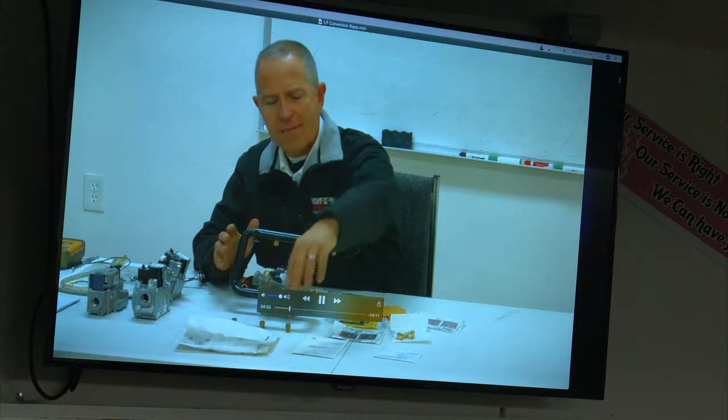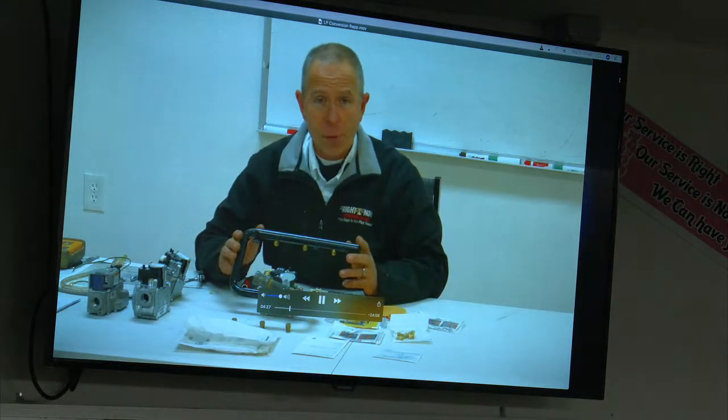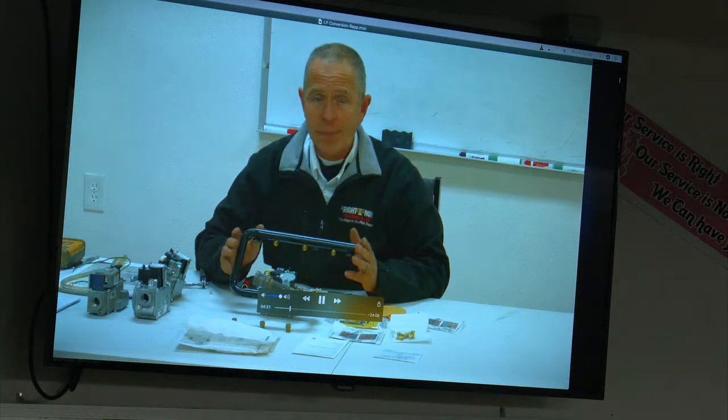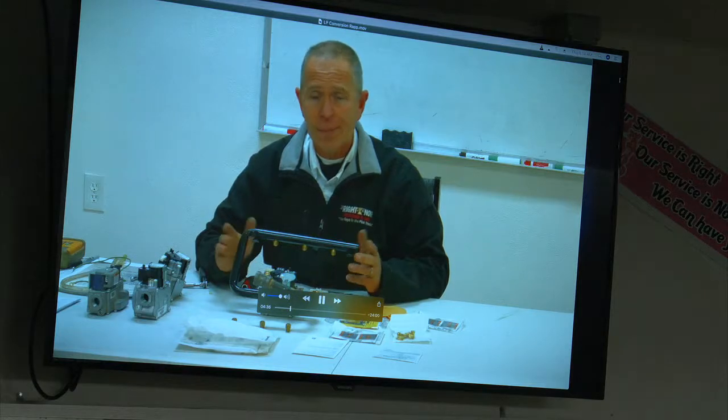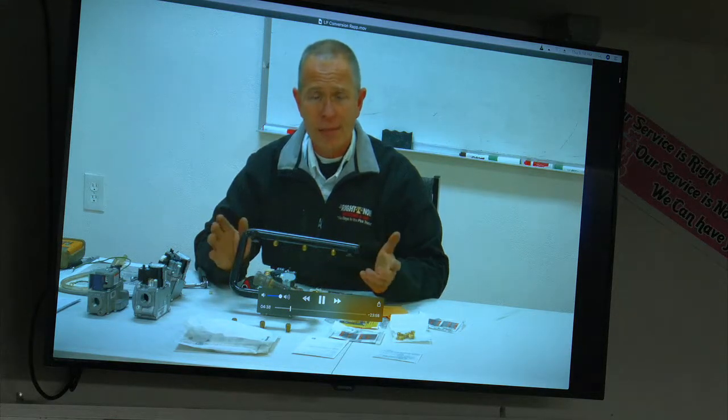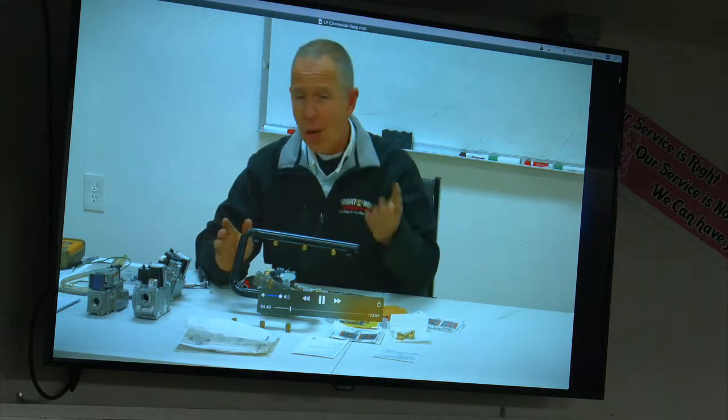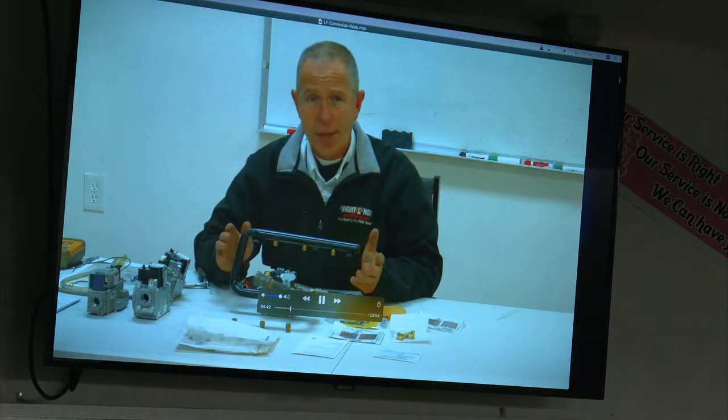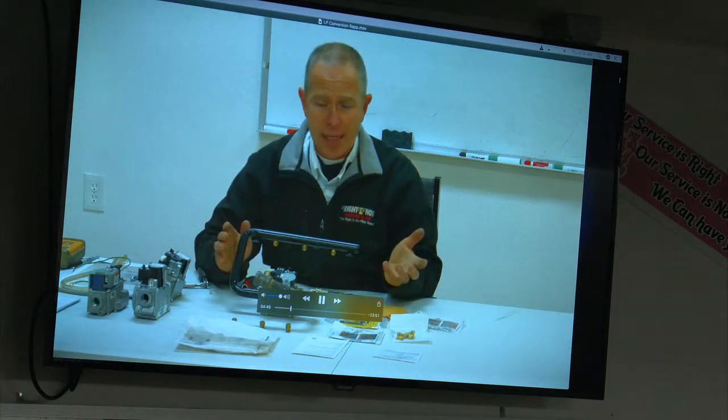So it might be an FP32 or an FP34, right on the box. Goodman doesn't do it quite that way, but it's easy to call Thermal and they can match up what kit goes to it. An 08 will go to a 96 variable speed, an 07 will go to a 96%er, and an 06 will go to an 80%.